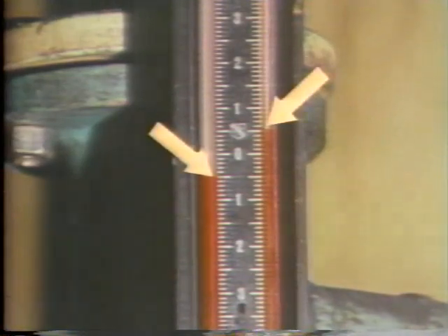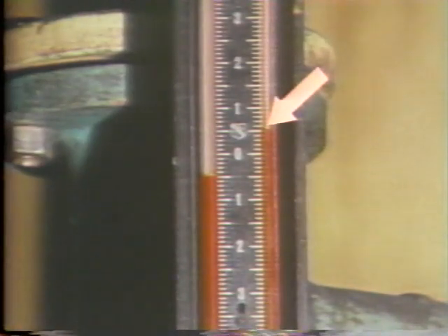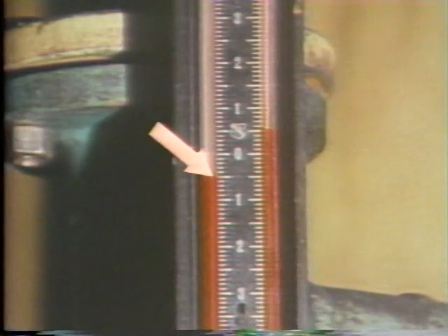To read the scale, you simply add the reading from both ends of the water column. In the case of this example, one end of the column of water, the one above 0, reads about 1/2, and the other end of the column, the one below 0, reads about 1/2 as well. Both readings above and below 0 should be the same. Otherwise, there isn't enough liquid in the manometer and the readings won't be accurate.